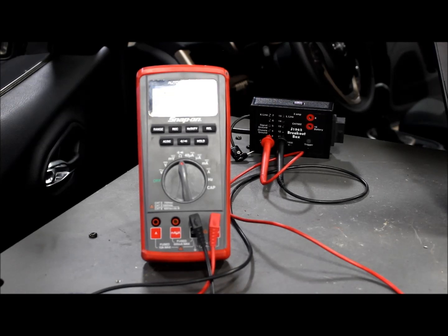When the bus is idle, about somewhere around 2.5 volts, and when the bus is active, the high will be 2.6 to 3.5, and the low will be 1.3 to 2.3. And then the IHS bus is a little bit different than that. So what I'm going to do is hook the battery back up and switch over to volts and see what we get.